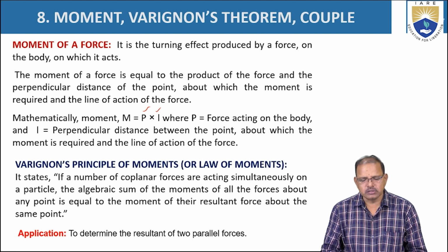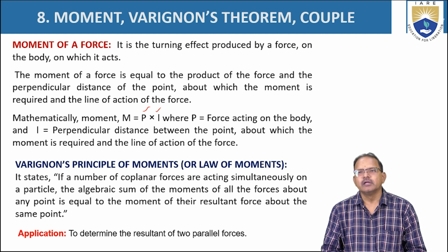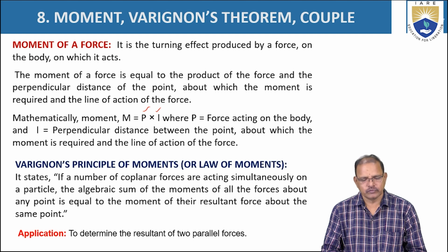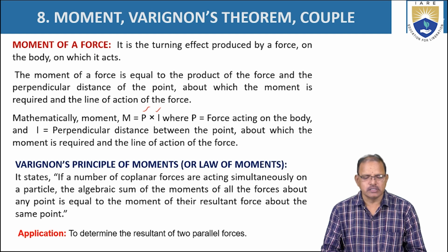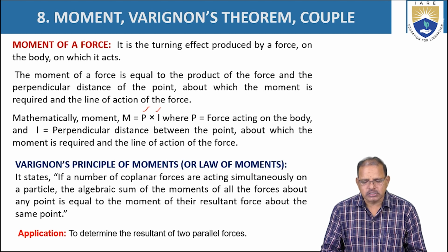Varignon's principle, also called the law of moments. Generally, it is useful for determination of the resultant of parallel forces acting on a body. It states that if a number of coplanar forces are acting simultaneously on a particle, the algebraic sum of the moments of all the forces about any point is equal to the moment of their resultant force about the same point.